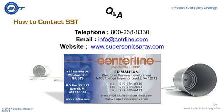Decorative finishes. I've got one customer who's using cold spray to apply metals such as aluminum, zinc, and copper onto glass surfaces. He's got one main industrial application in which he's applying cold sprayed bus bars onto glass. However, he's got a few applications where he applies the cold spray coating in a robotic design and then polishes these coatings to a very shiny surface. So he's actually using it as a decorative emblem application technique, where in the past he was probably using silk screen technology. So in certain circumstances, it does make for a beautiful aesthetic design coating.